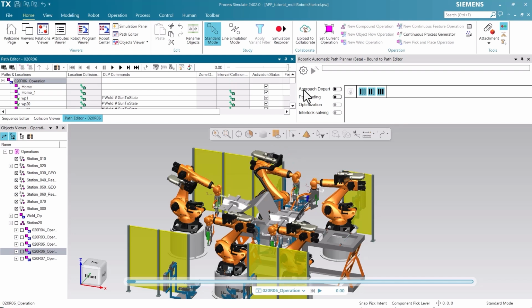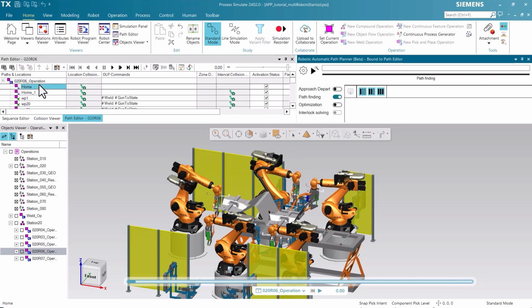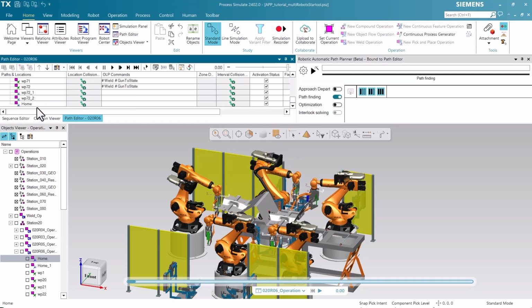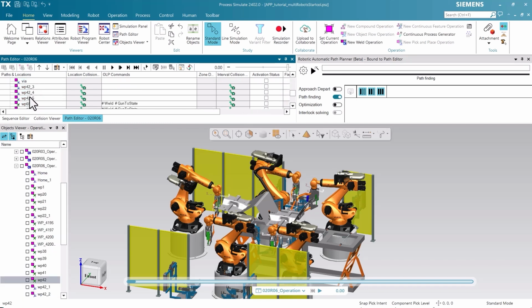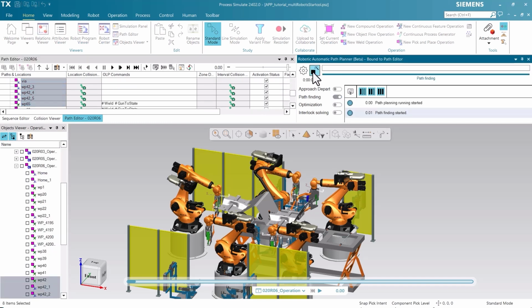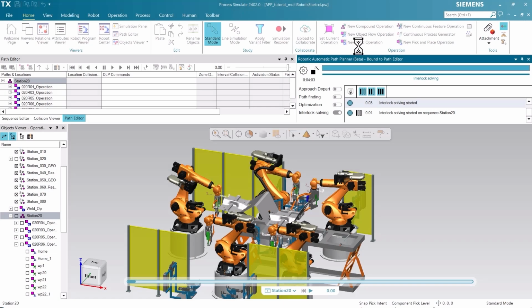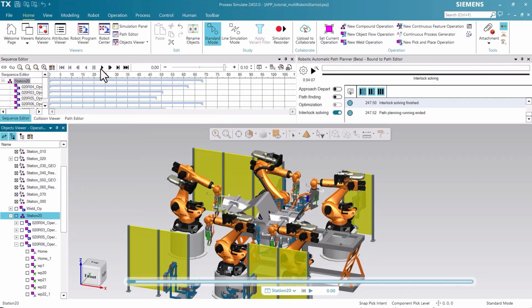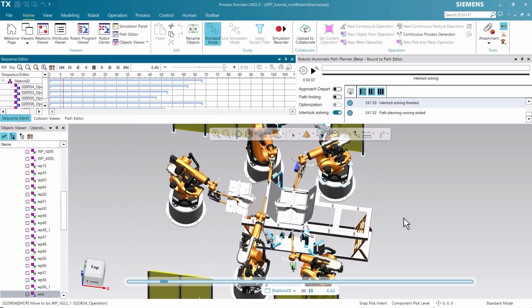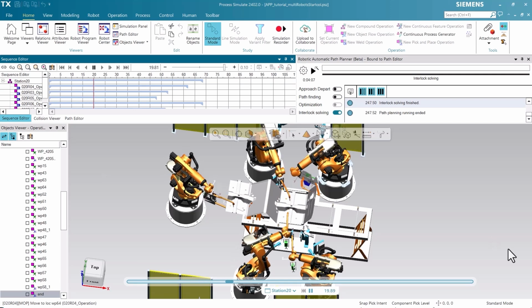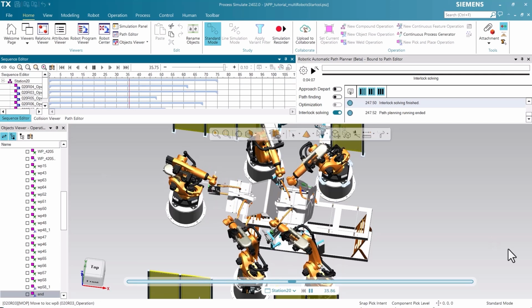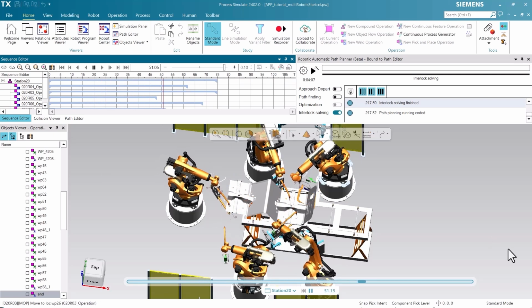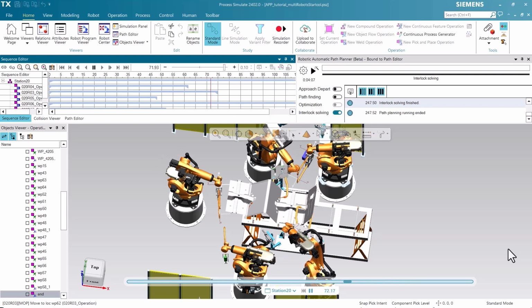By simulating the operation, we can understand the interaction between robots, tools, and parts, which can be difficult in a physical setup. Simulations give us detailed data which can be used in identifying and implementing process improvements. By visualizing the robot's movements in this virtual environment, potential collisions or reachability issues are immediately apparent. Doing this before any physical implementation helps to reduce costs and save time.